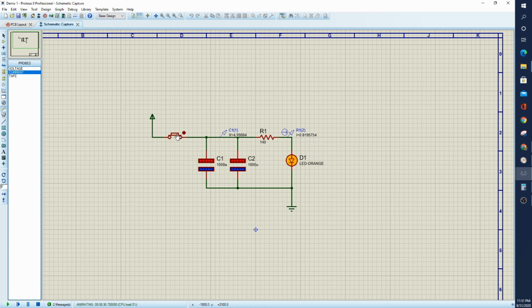And so now if I click on the button, it opens up and we can see the voltage dissipating as the current goes through the LED and sinks down. And we shouldn't see it go too much further down. And the reason being is there is a breakdown voltage here on the diode. And so this is fantastic. This is telling us exactly what we would see in real life. Just the bleed through current will continue for a while, and perhaps eventually it would reach 0. But press it again and the LED again brightens up and then dims down.